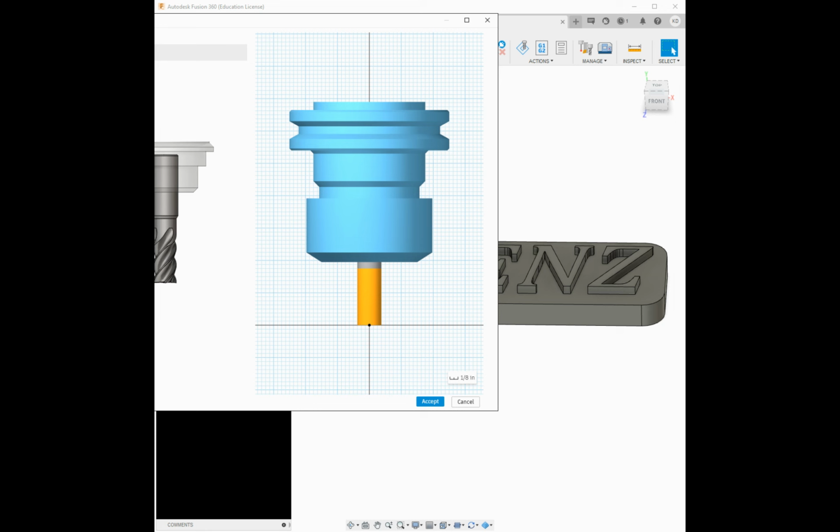And if you don't know what to put in here, remember this is the specific geometry of the cutting tool itself. There's no special answer to this. Look at the tool, measure the tool. A lot of tools will come with this information on the package, assuming it's not loose in a bin somewhere. So that is a great place to look for that information, and also a good reason to keep it. And remember, the cutting data, this is what we are actually calculating. So this is what you know how to calculate from our formula page.